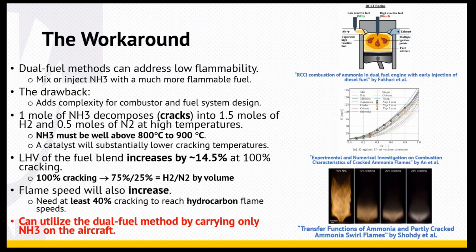Also, typically, let's say maritime engines like cargo ships that are being worked on to be fueled by ammonia, they use diesel as the pilot fuel to help get the overall bulk ammonia ignition going. And the issue with that is now you're adding a carbon fuel to the mix, which directly goes against our mandate.